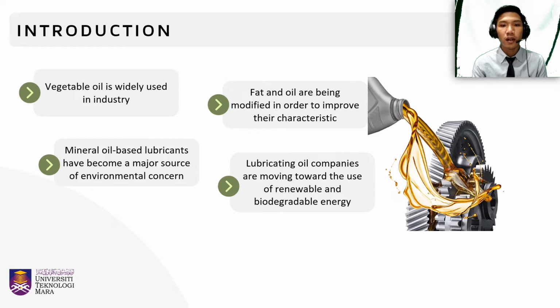Nowadays, vegetable oil is widely used in our industry, including in manufacturing, automotive, and other sectors. Unfortunately, in their original form, they have poor performance when exposed to high temperatures and pressures. They may oxidize and suffer chemical and physical compositional changes. Thus, fat and oil are being modified in order to improve their characteristic performance for their functions and applications. Employed modification techniques are fractionation, hydrogenation, and transesterification.